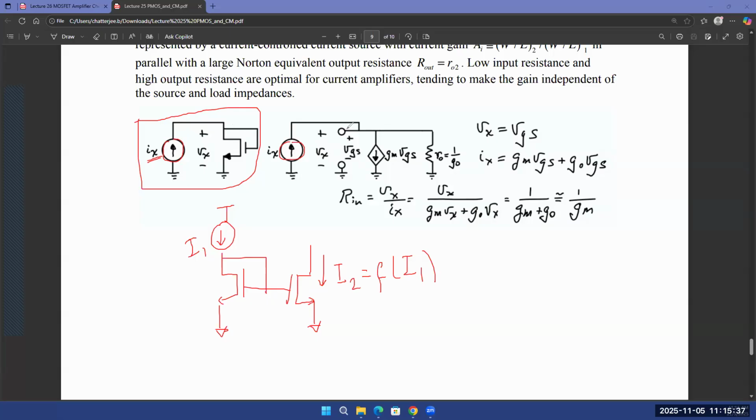So if this is my small signal circuit model, I'll connect my gate and the drain together. This connection is generally not there in the MOSFET, right? Drain and gate are not connected together. But because this is diode connected, physically you are connecting the drain and the gate terminal of the MOSFET together through this wire, and that is where you are applying your IX. Now, you can do the analysis with RO as well, and that will just increase the complexity.